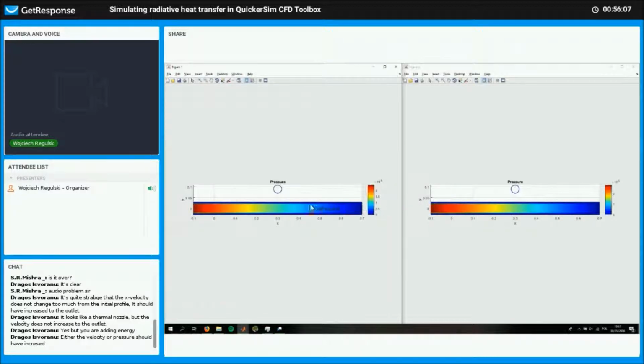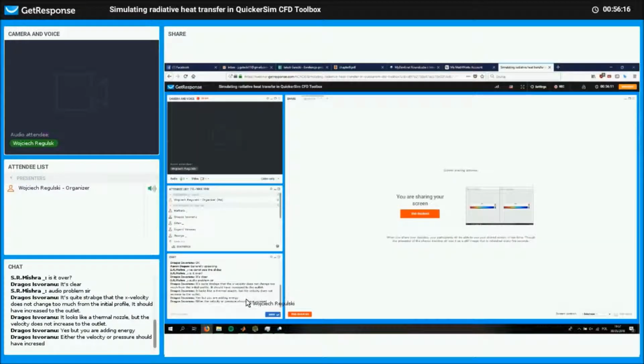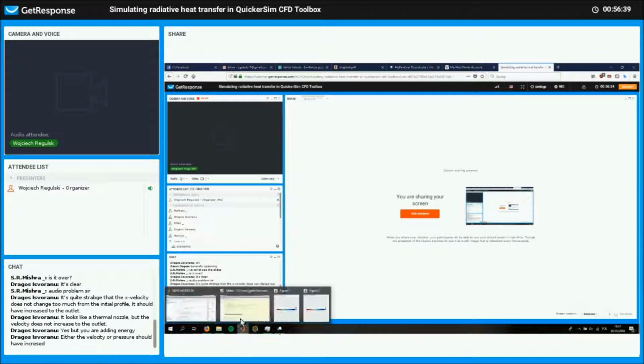You can see the difference in the angle of the pressure isolines, or the pressure contours, because once again we have flow going downwards a little bit. All right, so it also depends on the Reynolds number. This flow is actually very slow, so the effect is there. It's maybe just not very visible. You'd have to fine tune the parameters. Once again, my goal here is not to explain everything, it's more to just explain the solver.